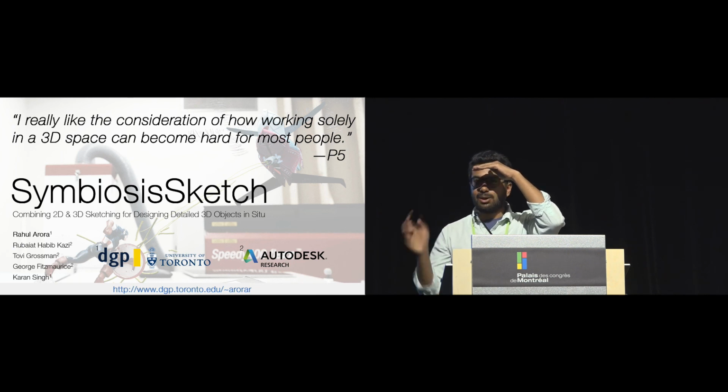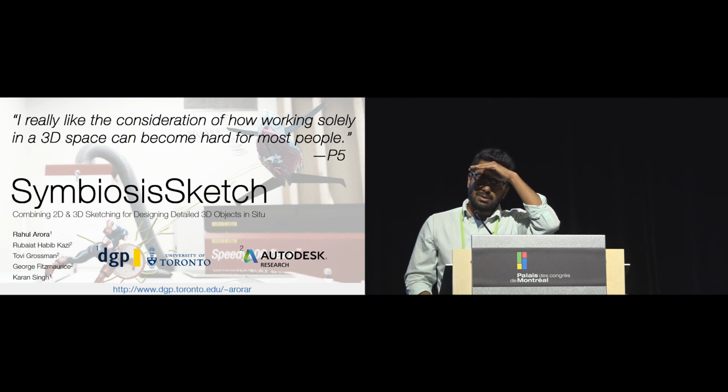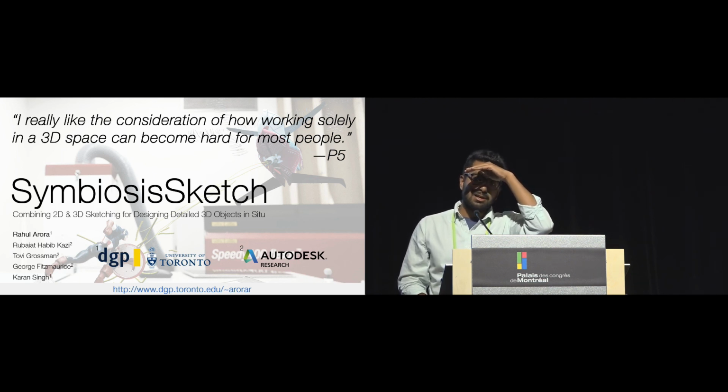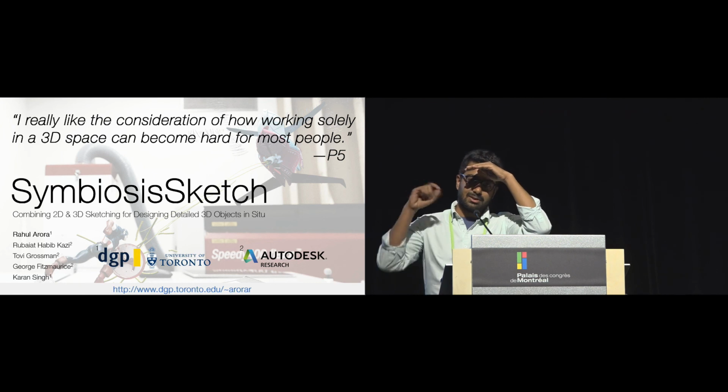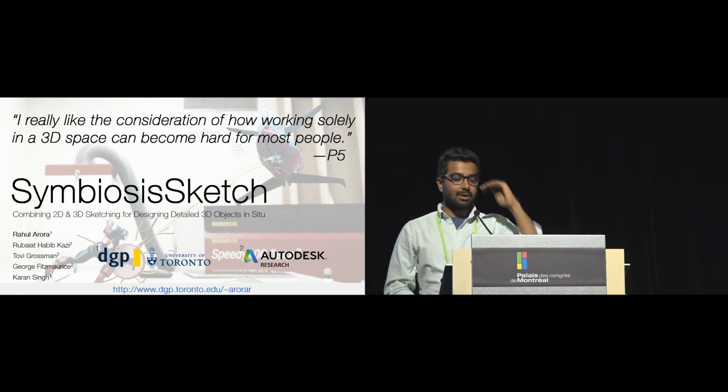You can't have a closed surface in the system. It's all open surfaces. So in order to draw a ring, I would probably select a plane which is aligned with the camera, or orthogonal to the camera view, and then draw a disk from the top. Yeah, and that'll be automatically selected. We don't have an interaction to actually manipulate the camera independently. Okay, thanks.